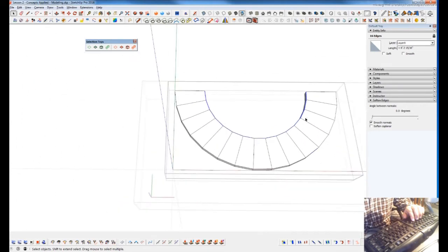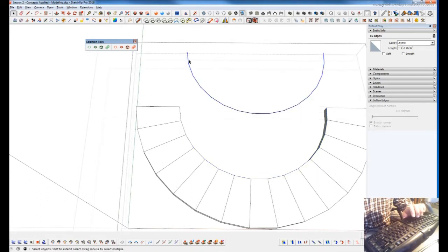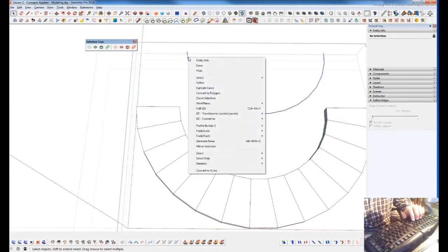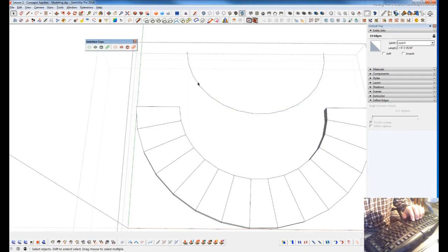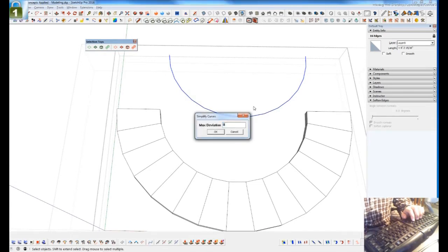It's not like a vector drawing program where you can make true curves. Everything is straight. And when you get into selecting, it's why sometimes I pull this out and explode this curve. Now these are all a series of edges, and these curves and curved surfaces, especially in what we do in the landscape industry, become a pretty routine part of the business, and selecting them is very important. So I'm finding a way to do that with the path select tool by double clicking. It also allows you to get down. You can weld this now very quickly.